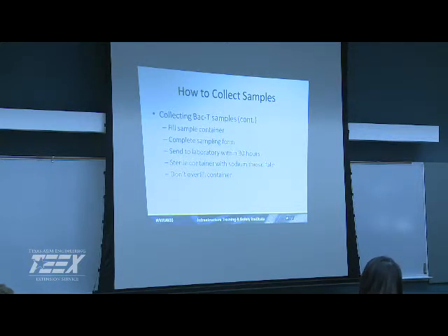But I agree. So we don't want to overfill it, and then we need to say the type of sample. I know we had a conversation about if you're actually doing repairs on your mains and it's back in service, now it's part of your monthly sampling and part of your MCL for your month instead of a special sample. So you can have construction that's not in service, or you just have your normal distribution samples, correct? So that's an important component of it now.